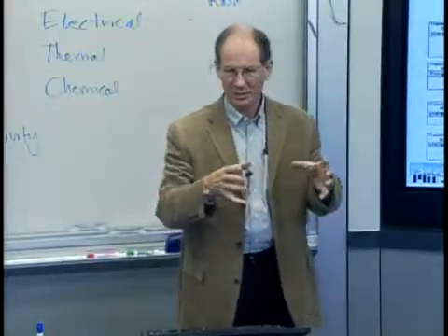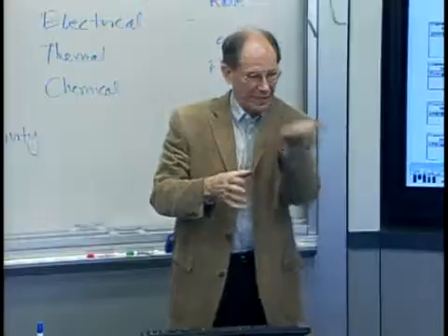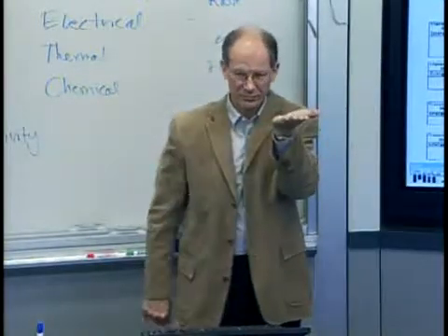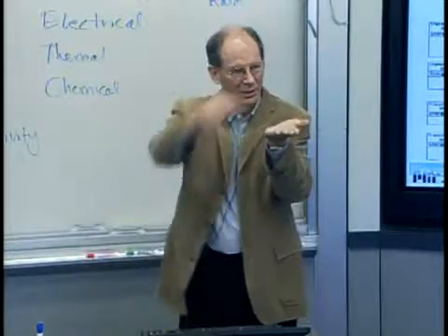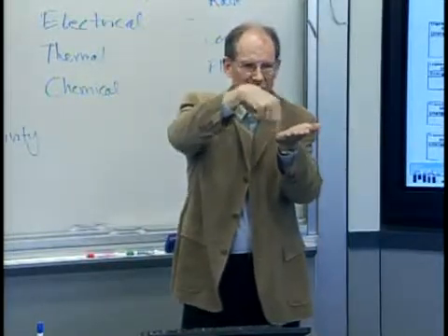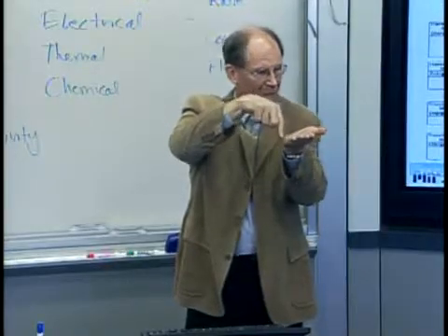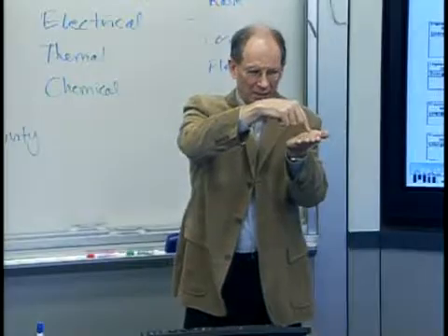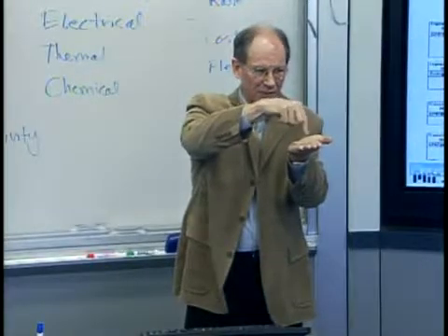And what you'll see is a bath of nearly colorless liquid with a platen on it. The platen starts at the top with a very thin layer of fluid on it. And this laser, usually not visible, will be dancing across the surface, tracing an outline, and that outline will become solid. Once it's polymerized, it moves the platen down and does it again.